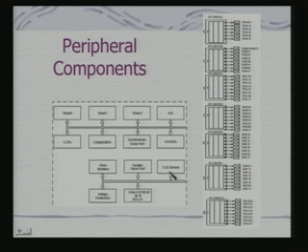One is LCD drivers, because typically if it is a standalone device it would require an LCD display. So, on the microcontroller itself we have the integrated form of LCD drivers, so that I can directly have the LCD display interfaced with the microcontroller with a minimum of additional circuitry. Similarly, I have the other ports. Okay, you will find synchronous serial ports as well as USARTs. This is for the purpose of having serial ports implemented for communication, maybe with a PC and other devices.